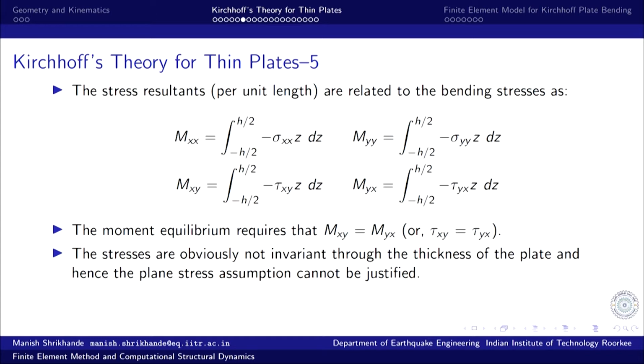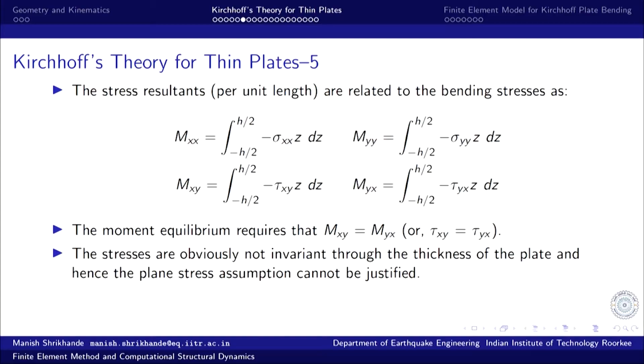Although the deformation w, the normal deformation of the plate, is considered to be invariant through the thickness, the stresses obviously are not invariant through the thickness of the plate, and therefore the plane stress assumption is not exactly valid. But we resolve this problem by considering each lamina of the plate, that is plane at a constant value of z, to be in a state of plane stress, as I mentioned earlier.